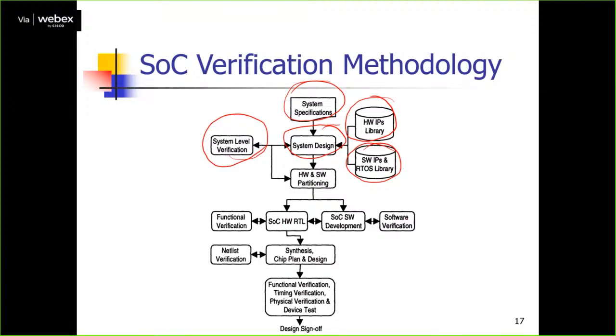The RTL will take initial steps, and from here it goes to an ASIC flow. So you look at the ASIC flow. You have an RTL design, you do a functional verification, you do a synthesis, generate a netlist, and verify it. Then you add constraints to the synthesis and do the netlist verification. It goes for PD.